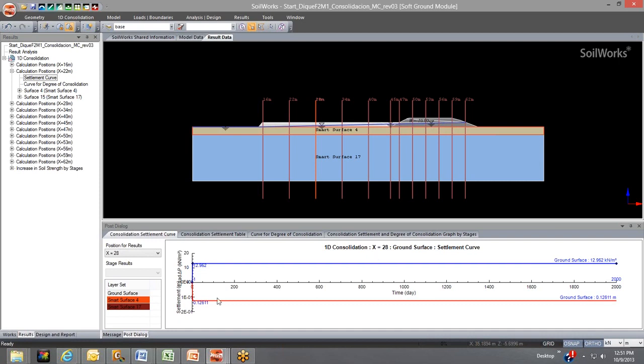So it's just straight. And this red line here goes over your displacement or your settlement. As you can see, there's immediate settlement, and then it just stays the same throughout. Even though this is a clay layer, the load isn't sufficient to get it to consolidate or settle past its immediate settlement, so the line is straight. If the load was large enough to cause the clay to consolidate very slowly over a long period of time, this would be a slight curve going down, like so.